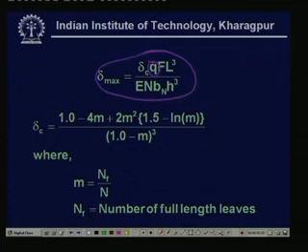However, normally these laminated springs we are designing are thought of as a double cantilever centered at the middle. Anyway, our idea was to find out what the correction should be by putting the full length leaves below the master leaf.